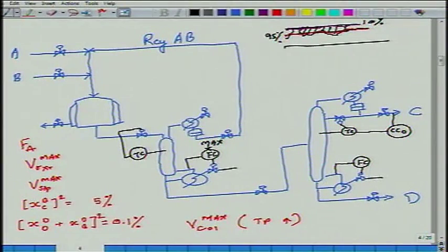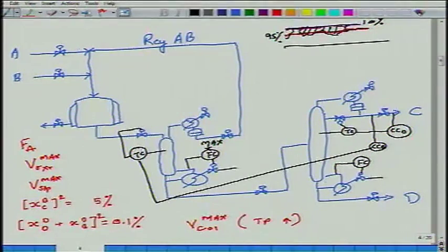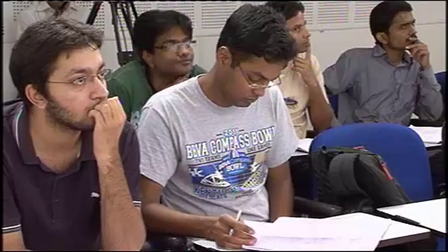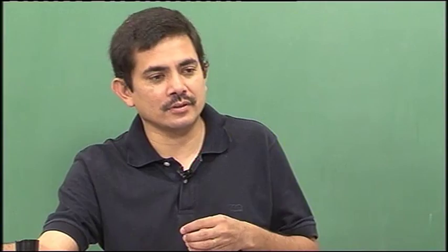Now you are going to say, well, temperature doesn't exactly control composition, which is true. Since I want product quality, I measure; my lab will tell me how much B impurity is going in too. And then I will say, if benzene is increasing, temperature will ensure that much does not leak. Anyway, you are getting those composition measurements twice in a shift.